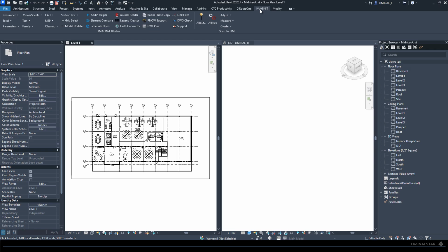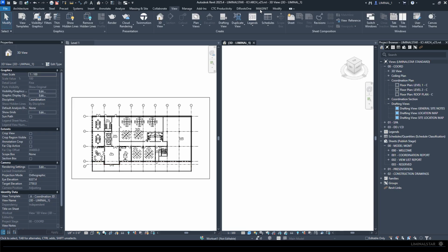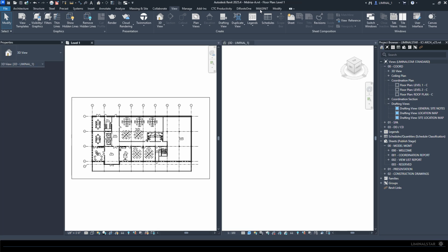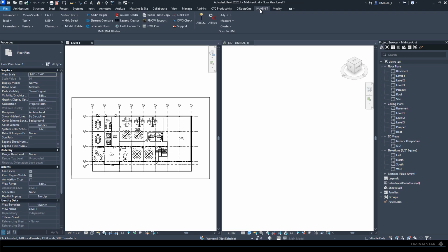We don't have work sets in this file, so you can see in my template, when I click on my work sets, it brings up a list. Over here, this was just work shared from a single user BIM, so I only have Workset 1 and Shared Views, Levels, and Grids. So I'm going to want to start to allocate to the different work sets that I use in my office. I'm going to need to put those in there, and I don't want to do that the old-fashioned way, so we'll take a look at that. And then the other thing, I guess, is line weights too. I'm going to probably want to bring my line weights over and my object styles so we can see if we can accomplish all of that in one transfer process.